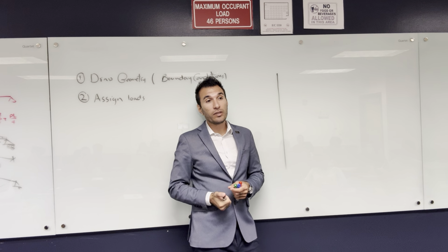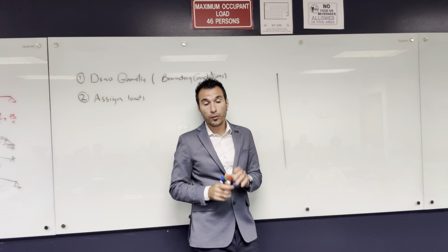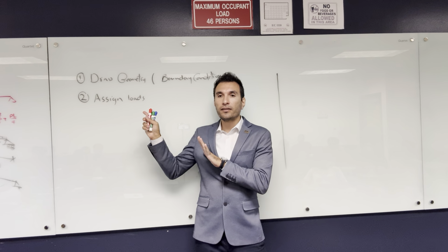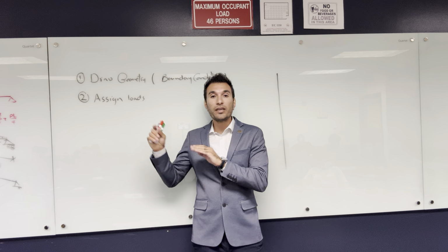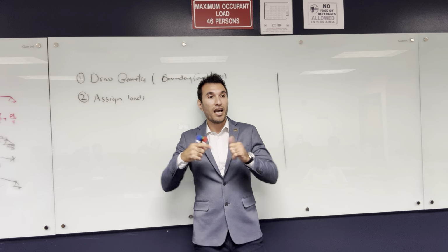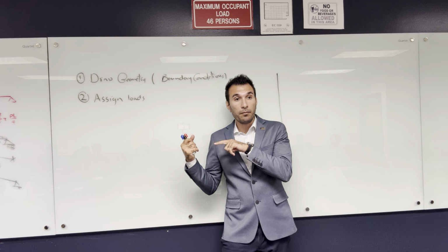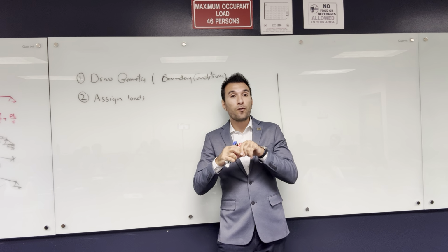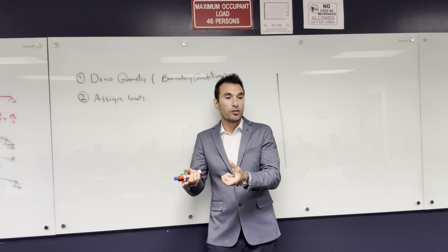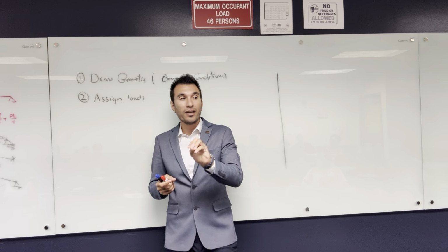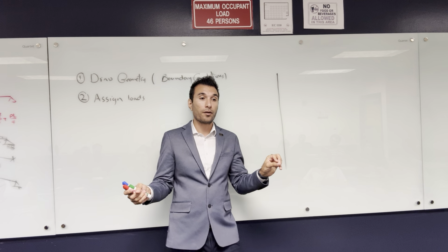However, in SAP 2000, or I believe most of the software, when you run it, you already drew the geometry and you defined that this geometry is reinforced concrete. So it calculates the weight of the reinforced concrete and runs the analysis based on the elements that you gave it, and you are going to have some internal forces due to the own weight of the structure that you built, unless you tell the software that the structure's own weight is 0.